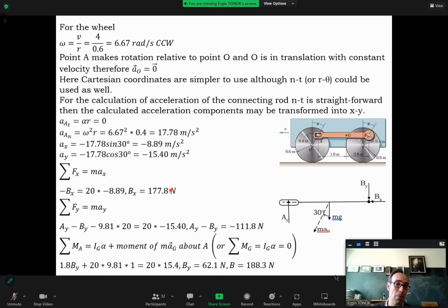That's good. But when I sum up the vertical forces, I have Ay upwards, positive direction, By downwards, so negative direction. And then I have the weight, mg, is equal to mass times the y acceleration. And I get a relation between Ay and By, but can't solve them individually.